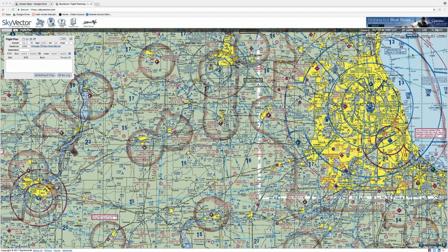Okay, I'm going to add one more to it. Vertical visibility. So if you are forecast broken, overcast, or vertical visibility, you'll see it as a VV on your METAR. That's what constitutes a ceiling. So I want you guys to say when you're asked this on the practical, because you will be asked this, a ceiling is defined as the lowest layer of broken, overcast, or vertical visibility.